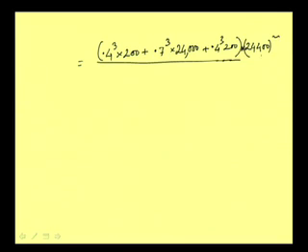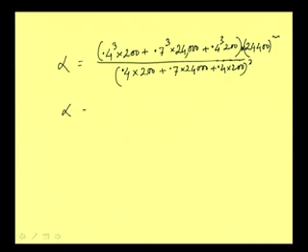So that way we are getting this total area square, and then here we are writing 0.4 into 200 plus that is what this area into velocity A1 V1, 0.7 into 24,000 plus say 0.4 into 200 again, and that is cube. So, that is what our alpha is. Then the alpha value, if we simplify this part, we get a value of 1.00775.